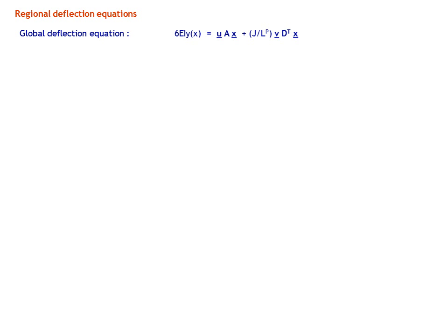In order to justify the claim that this deflection equation is, in fact, a global deflection equation, valid across the whole beam, it must be able to reproduce the three regional equations, to the left, underneath, and to the right of a partial load. These are normally derived separately, but I'll show here how they are all contained within the one deflection equation.